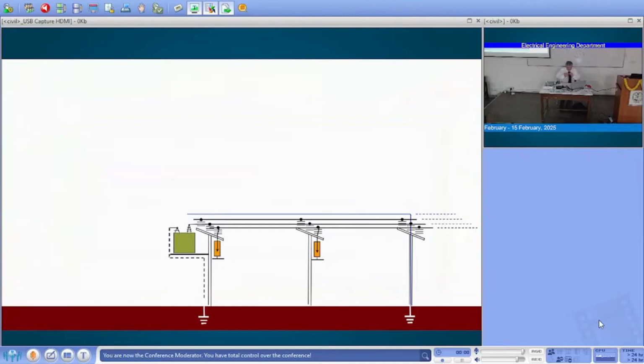And then you see the conductors. In some lines, not in all, there is also installed this wire above that is connected to ground, the shield wire, and these devices are the surge arrestors. So if the voltage increases too much with respect to the rated voltage, they provide a low impedance path to ground for the lightning current, and then there is the transformer.